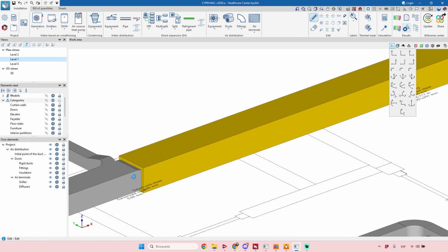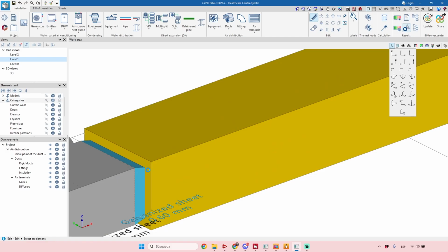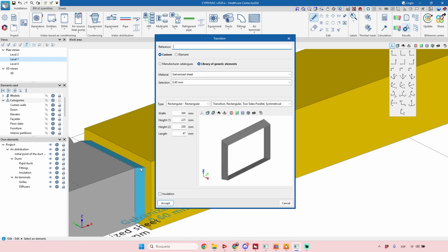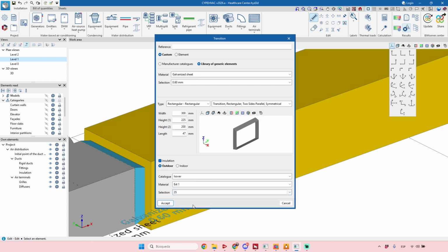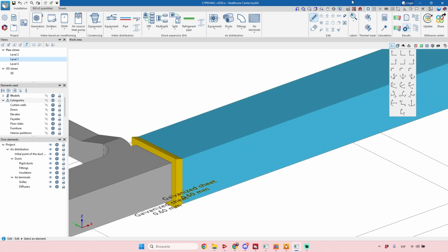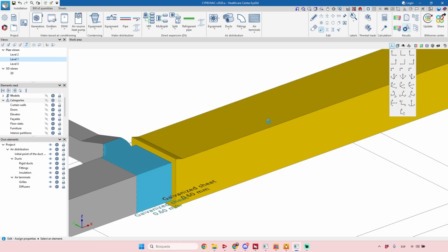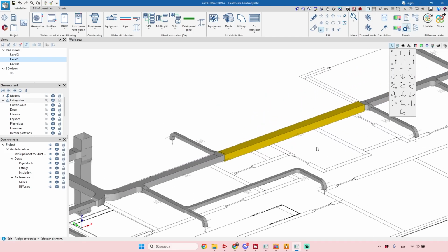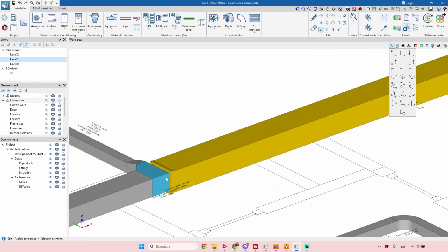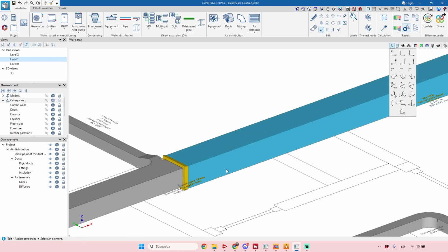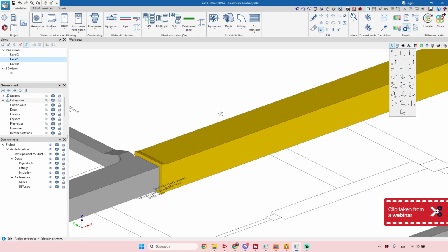Okay, it's nice because even if I have little pieces or sloped surfaces like this, I can activate this insulation. There is no problem. I just have to select the same one. Okay, or use the options that I have here to copy properties. There's somewhere here an option that is to assign properties and change some parameters here and apply the same parameter to everything. Okay, so the introduction of insulations or the modeling of these insulations is now also available here at CYPEHVAC.